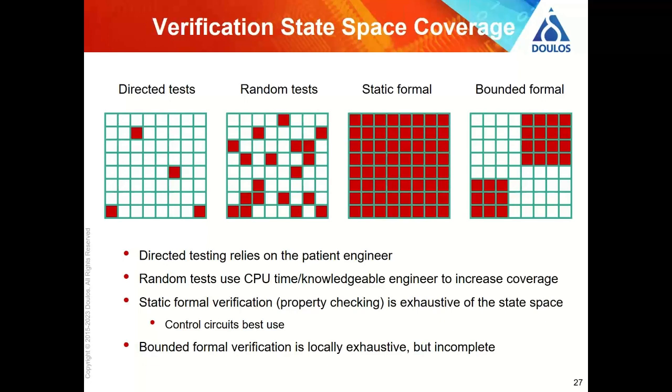With formal verification, we can comprehensively say every possible state has been addressed, because the formal verification tools use different techniques. They use symbolic analysis to work out whether properties are going to actually be true or false. So we can get a 100% pass or fail answer.